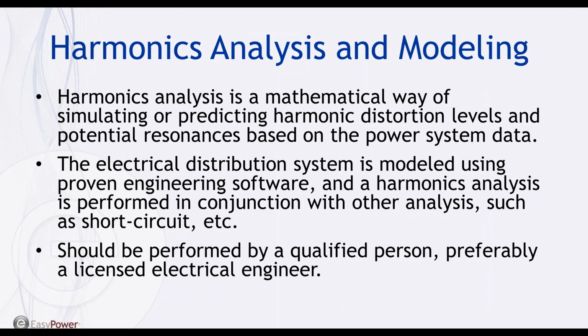So harmonics analysis is a mathematical way of simulating or predicting harmonic distortion levels and potential resonances based on the power system data. The electrical distribution system is modeled using proven engineering software, and harmonics analysis is performed in conjunction with other power systems analysis, such as short circuit analysis, etc.